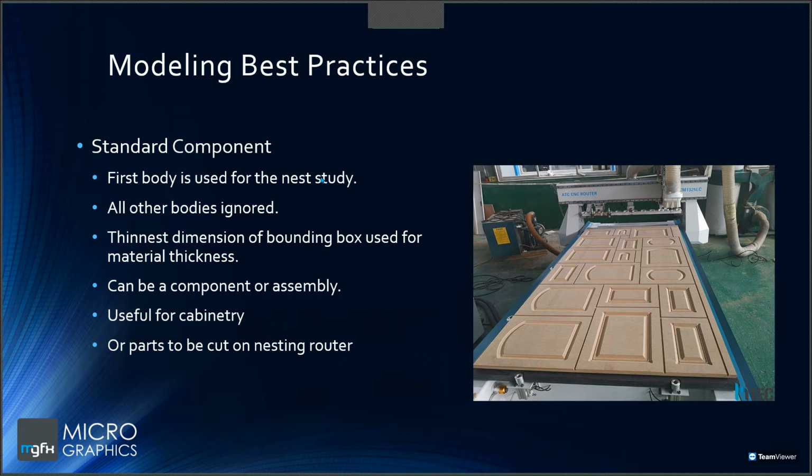That would conclude the best practices for both sheet metal components and standard design components. With that being said, you do need to be careful when creating a nest where you have things like hinges and handles and nuts and bolts and screws. You would need to exclude those from the nesting study, and I will show how that is done when we go through the nesting study setup.